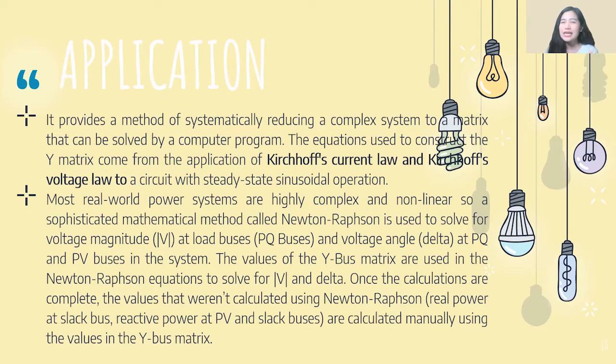So a sophisticated mathematical method called Newton-Raphson is used to solve for the voltage magnitude at load buses, wherein PQ buses, and voltage angle delta at PQ and PV buses in the system. PV, PQ, and so on are just designated names, for example, in algebra, the A and B, X and Y. So para bang sinasabi na this is bus 1 connected to bus 2, something like that.